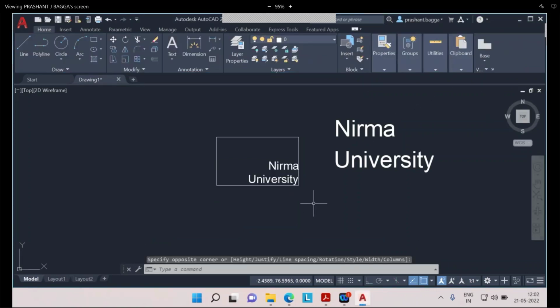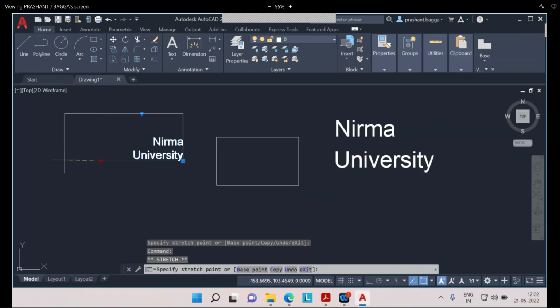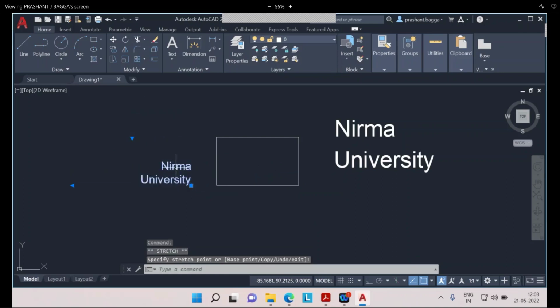So this is how you can create an M text, and there is some formatting style. And the second thing, when I select the text, I can move the text wherever I want. The whole multi-line text will be moved. If I increase the height, I can increase the box size, or I can increase on this side, and so on. Is it clear to everybody? Please answer yes or no.